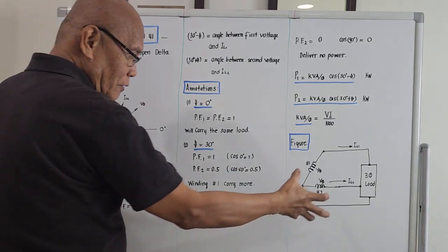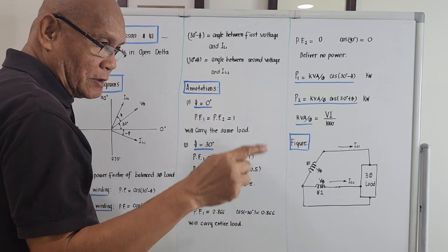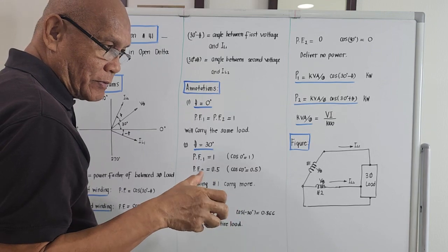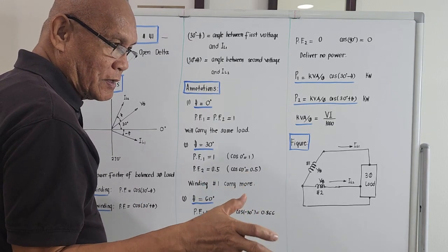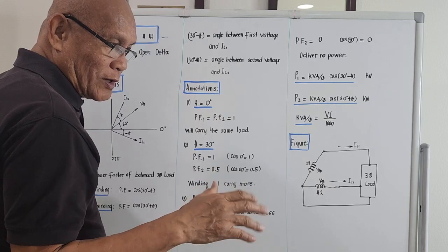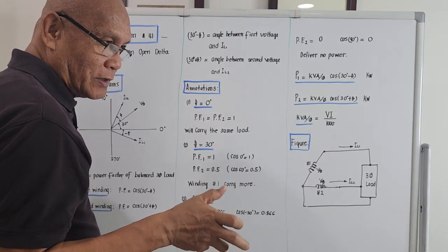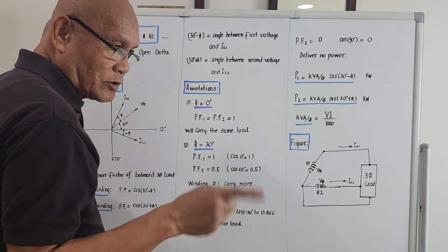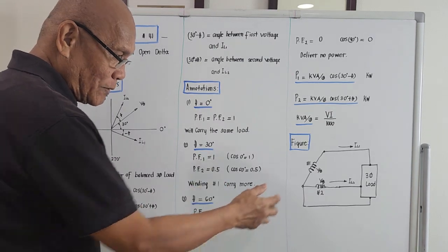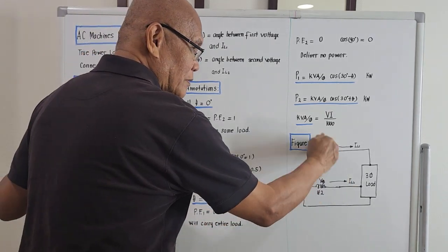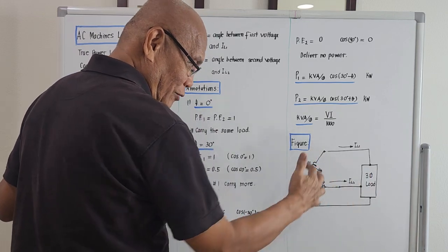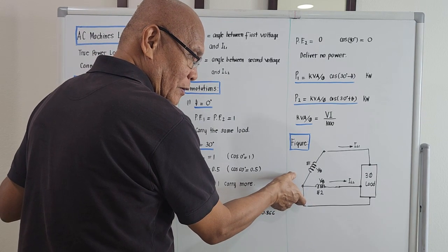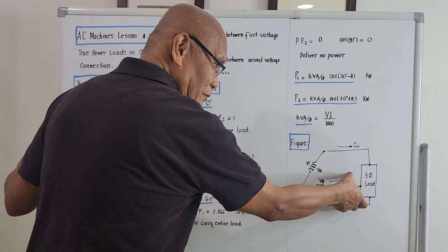We are given an open delta connection. We discussed already the closed delta and the Y connection. One of the other variations of connection under three-phase transformers is what happens if one of the transformers is damaged. We could still operate the two transformers, but the orientation should be an open delta. The third one is missing, it is for repair, but we could still use these two by using the so-called open delta connection, supplying a three-phase load.